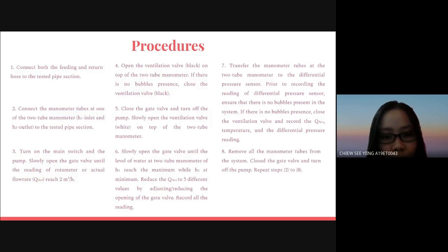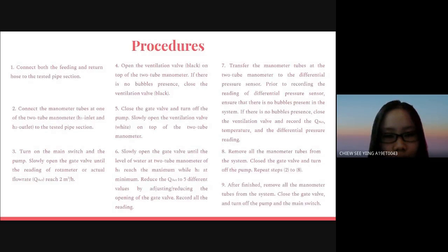Lastly, all the manometer tubes are removed from the system, and the gate valve and pump are turned off respectively before connecting the feeding and return hose to another pipe section. Repeat the steps above.